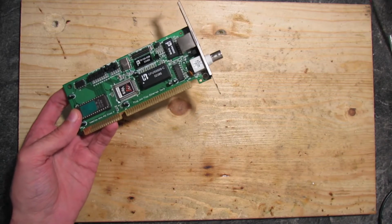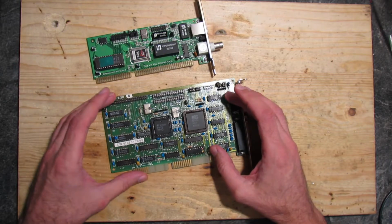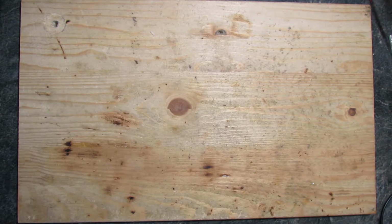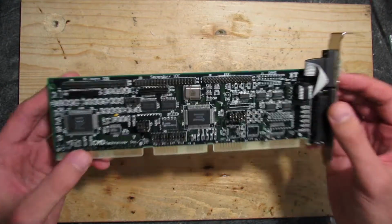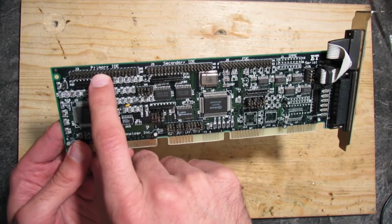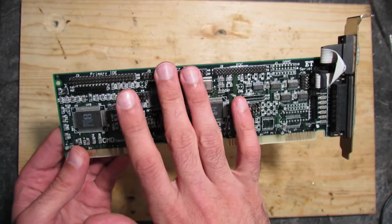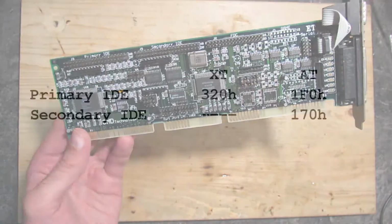We still need an IDE controller like this one. It has one IDE connector and it can accept up to 2 IDE devices as master and slave. Take a look at another IDE controller. This one is VLB, but it doesn't matter here. What matters is that it has two IDE connectors, the primary IDE and the secondary IDE. Each can be used to attach two IDE devices, so this IDE controller can handle up to 4 devices altogether.